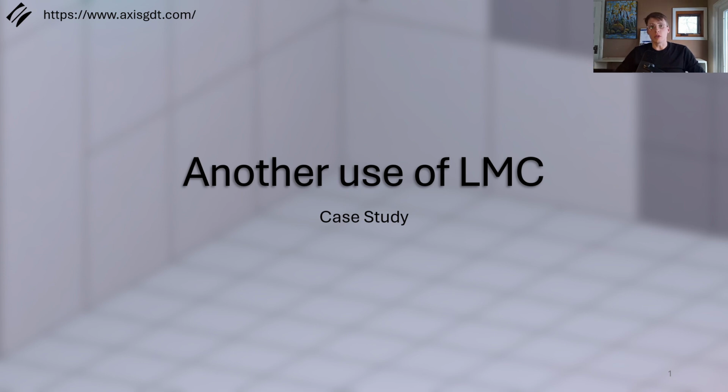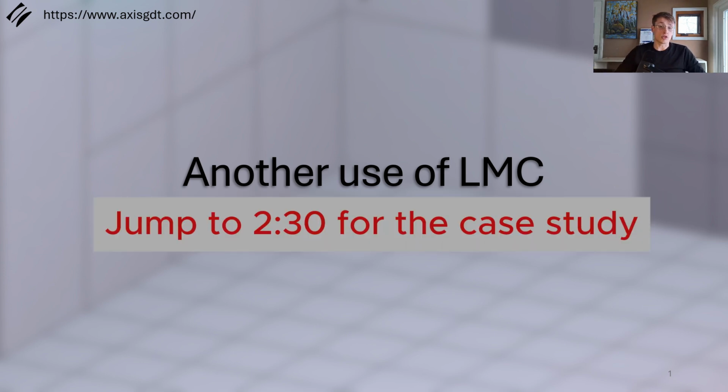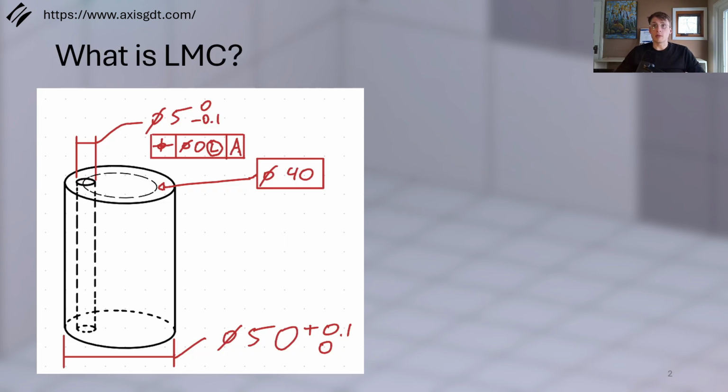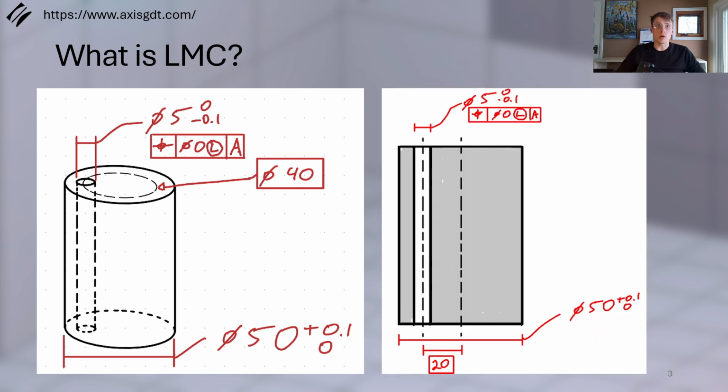And before we get into it, I'll just review how LMC is traditionally used. So LMC is typically taught as a material modifier that is there to control a wall thickness. Let's say we had a part with a hole and we don't want to get some super thin wall condition because that hole is pressurized. Well, typically we'll apply some sort of LMC positional tolerance to the axis of the part, let's say.